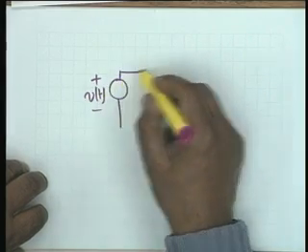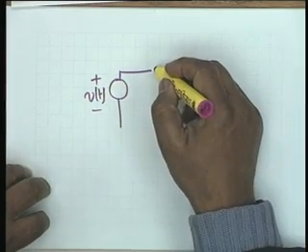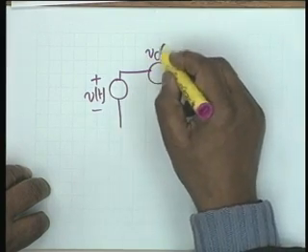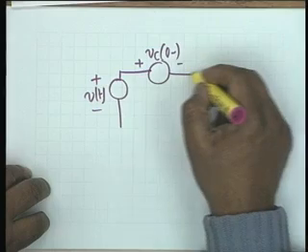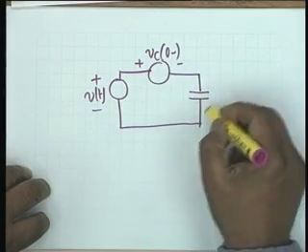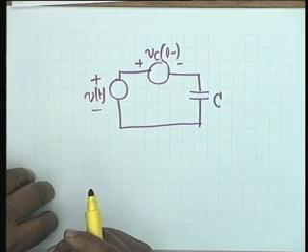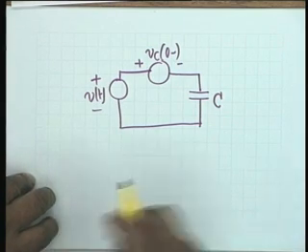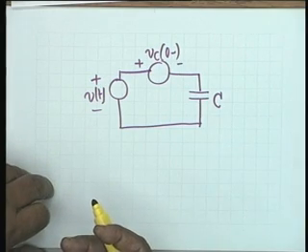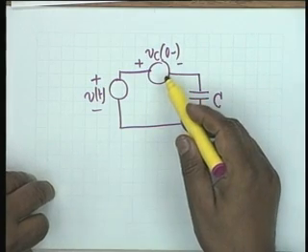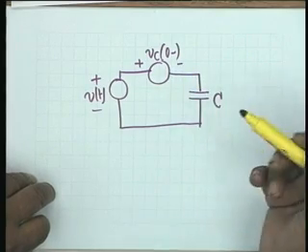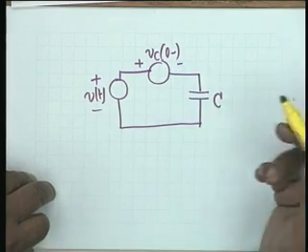an equivalent circuit in which there is a source. You see, Vt is the sum of Vc 0 minus and the voltage across the capacitor initially relaxed. The equivalent circuit of a capacitor is therefore the series connection of an ideal voltage source and an initially relaxed capacitor. I hope this is clear by the same arguments.